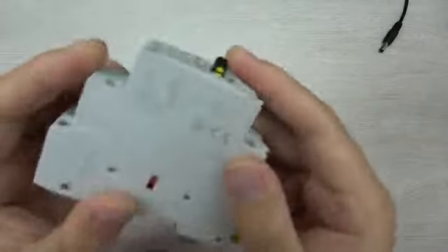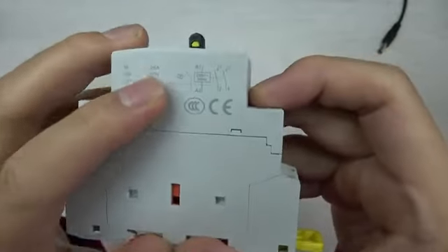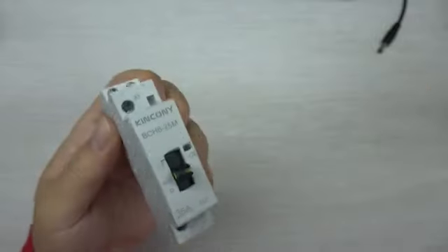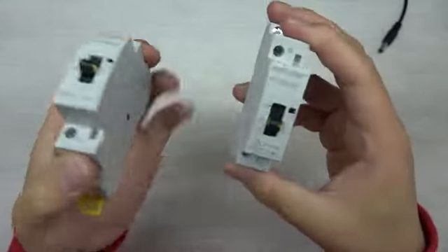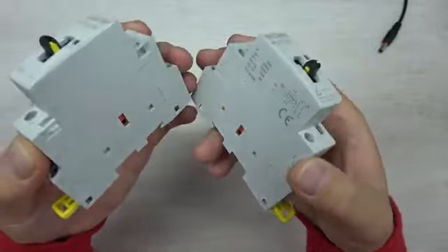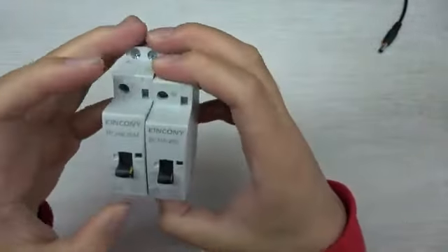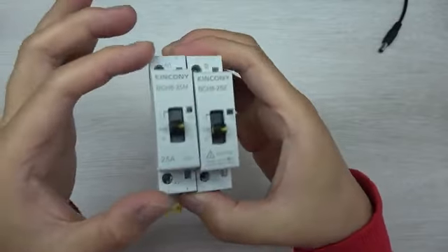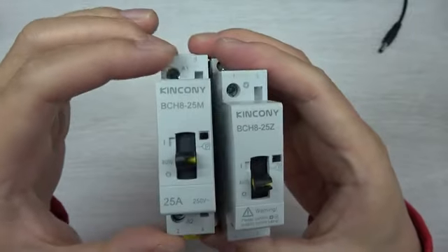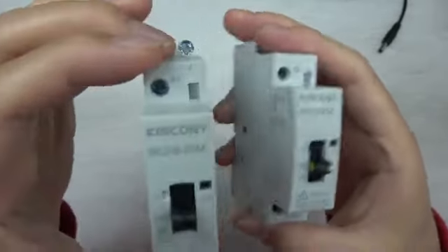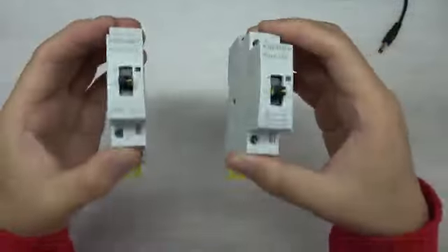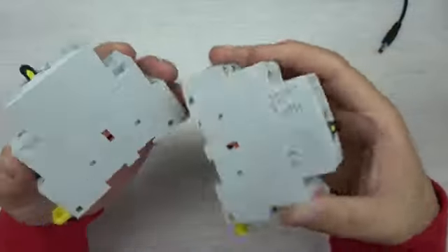And this one is an AC contactor. You can see this is also 25 volt, but this coil is AC 220 volt. Just this one is DC and this one is AC. The appearance is the same as each other, just with a different working voltage for the coil. This one you can see has a positive and negative because it is DC, but this one has A1 and A2 because it works with AC. So they have different control voltages, but the same functions for the contacts.